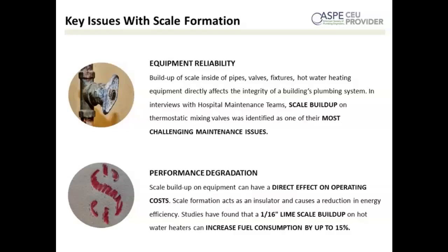And then there's also just a performance degradation issue that can really have a direct effect on operating costs. So scale acts as an insulator and causes a reduction in energy efficiency. And some studies have found that up to 1/16 of an inch of limescale buildup on hot water heaters can increase the fuel consumption up to 15%. So degradation is definitely front and center as an issue when scale is left untreated. Next slide.